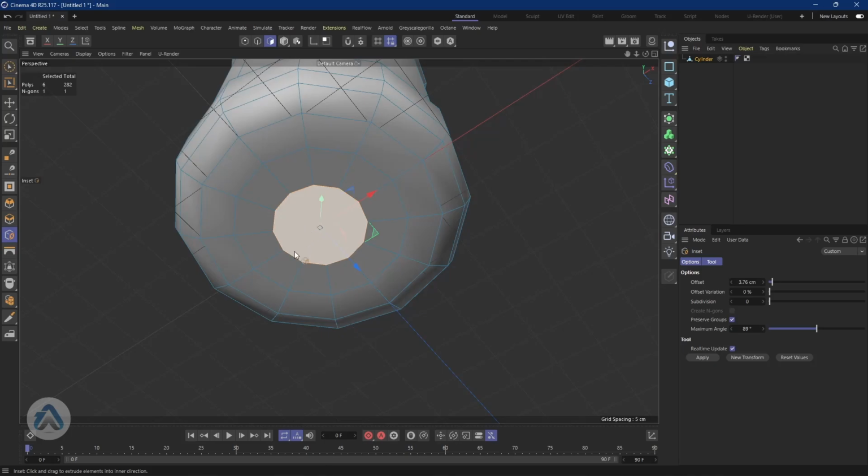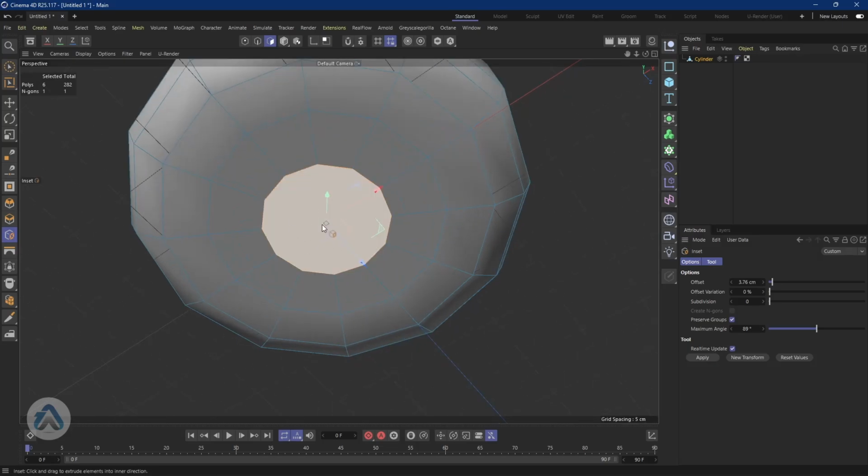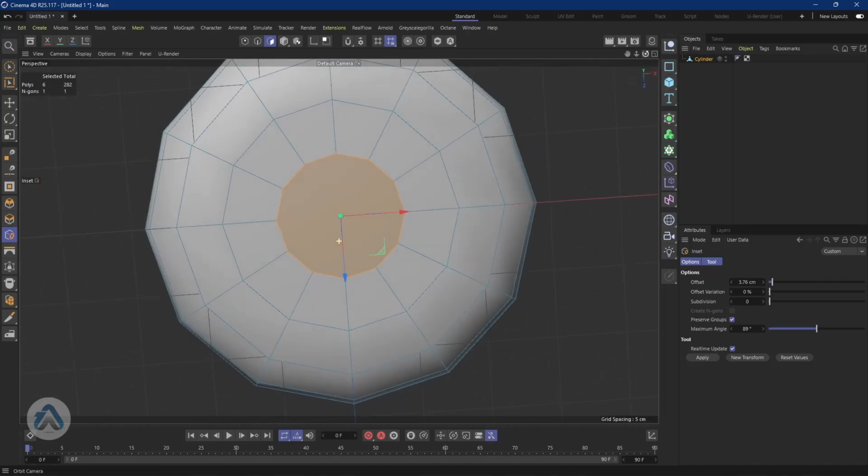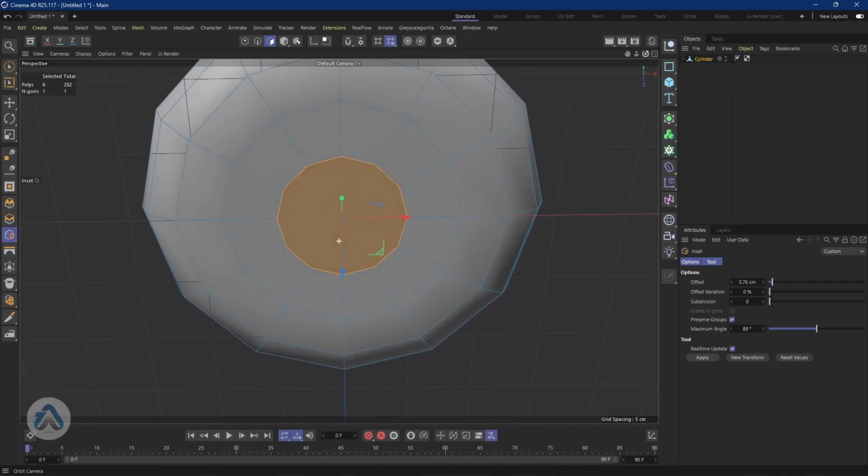Now we need to cut this polygon so that we can have quads. The same way these all have quads, four sides, like 1, 2, 3, 4, we need to make sure that the polygon faces here also have quads. Okay, so I want to align it like this so that the X side is facing the right.